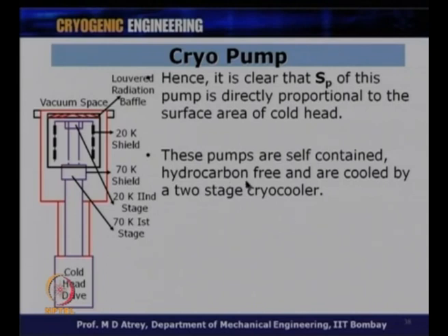So, there is no oil business over here, and therefore, it creates a very clean vacuum, and this is the way they can really be used in applications like semiconductor physics and microelectronics. Cryopump is a very acceptable pump in this area because it delivers a very clean vacuum. There is no oil like there is in diffusion pumps.